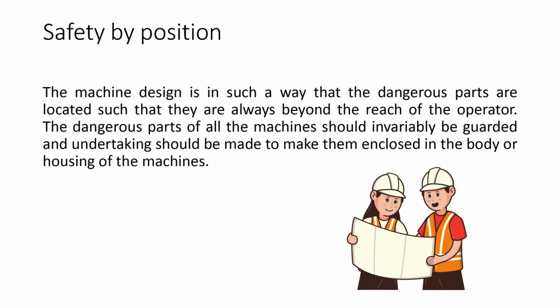Next, safety by position. This means the machine is designed so that the dangerous parts are located in such a way that they are always beyond the reach of the operator. The goal is to make them enclosed in the body or housing of the machines.